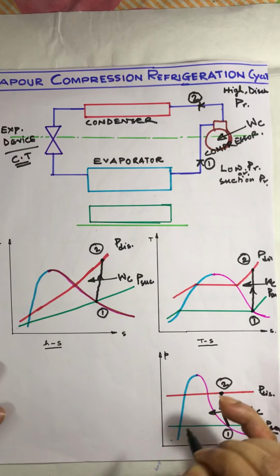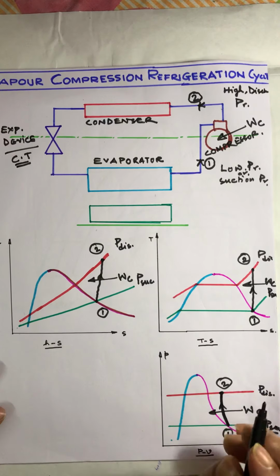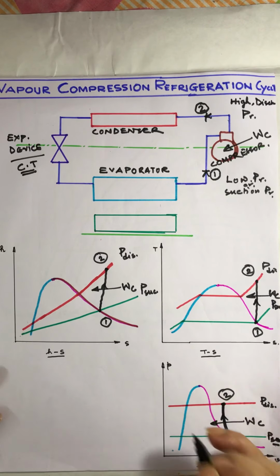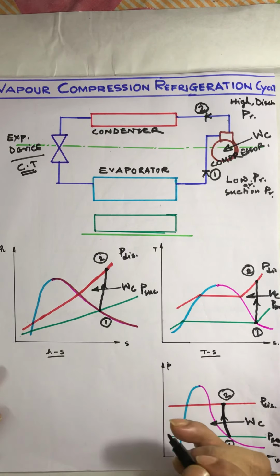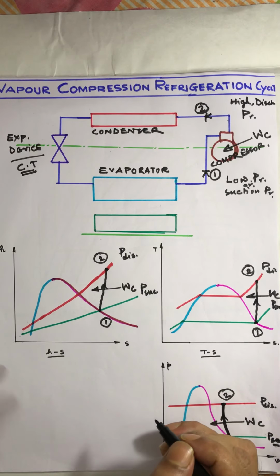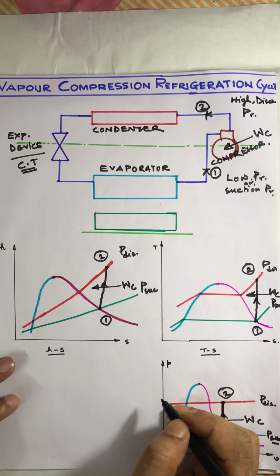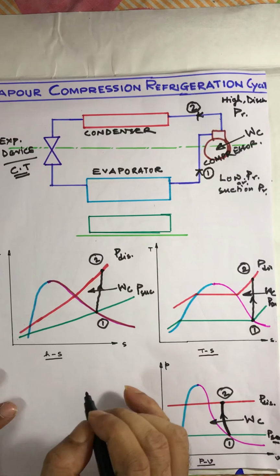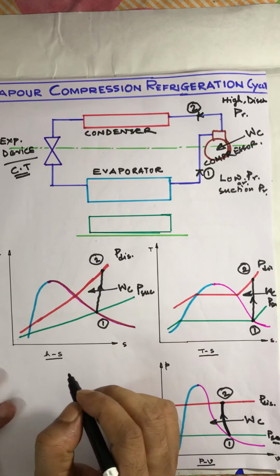for that high pressure, the boiling point of the working fluid will increase, and the temperature of the working fluid will be greater than the atmospheric temperature. Due to the temperature difference, there will be heat transfer from the condenser, and heat will transfer until, for that particular case, the fluid becomes saturated liquid.